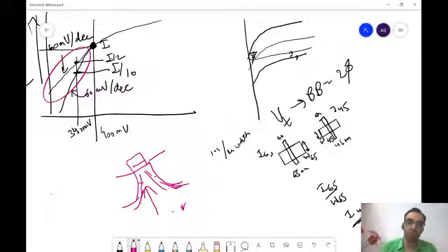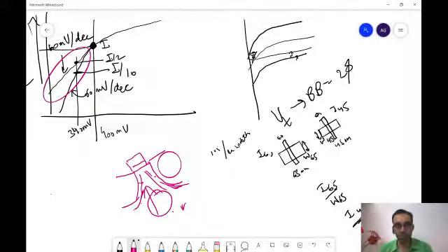Now, you still have to maintain a ratio between doping over here and doping over here to get transistor behavior. So many things come into the picture, and all this is VT engineering, which I'm not sure you will do in solid state devices at all. You will probably think of it in the Introduction to Nanoelectronics course, INE. There are halo implants, super halo implants, many different kinds of things which come into the picture.